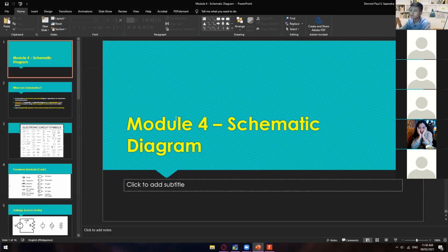None, sir. And one more thing, Miss Dulay Santiago, am I right? Yes, sir. When it comes to connection, just make sure that the maximum voltage of that component will not be overloaded. For example, it can only accommodate up to 5 volts or 12 volts, so do not put a supply directly connected to a 24 volt supply.